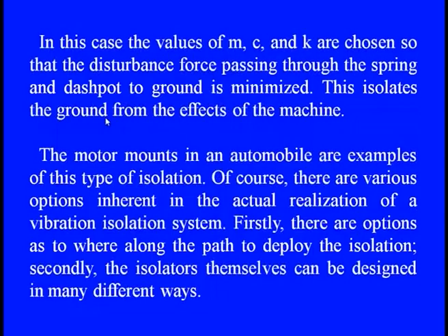So, if we are talking in this case, we can straightaway put the value of mass, damper and stiffness in such a way that whatever the disturbing forces coming out from any source, we can choose the damper, the mass and the stiffness just to diminish this entire vibration generation at that point. Because ultimately our main feature is not only to control the excitation vibration, but also to isolate this propagation path, so that the vibration or the sound level should not reach the ground or the surrounding as a kind of disturbance.